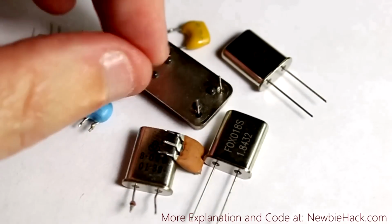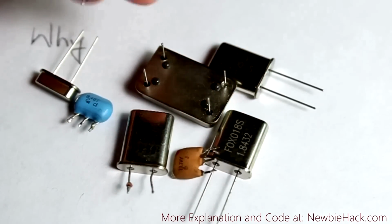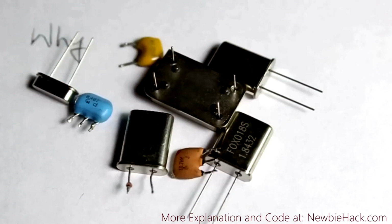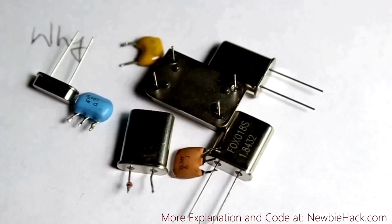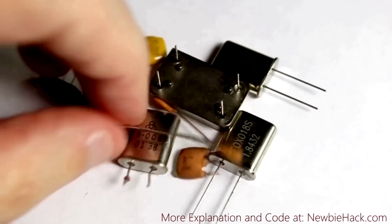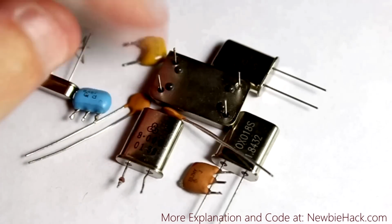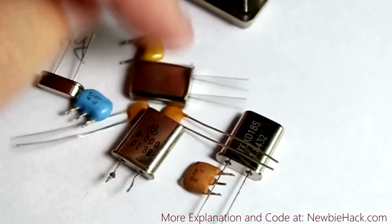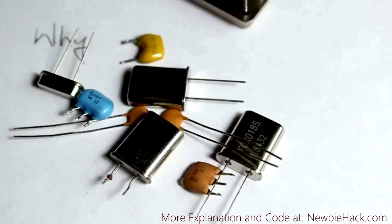These are what clock sources look like. These are crystals, the ones in the metal casing, and the ones you'll see that kind of look like capacitors. These are resonators, ceramic resonators. To make sure that these clock sources operate at the correct frequency and that they're stable, we'll also need to use capacitors. Capacitors are selected by manufacturer suggestions on the actual crystal or ceramic resonator and the residual capacitance that you have on your PCB or on your breadboard.